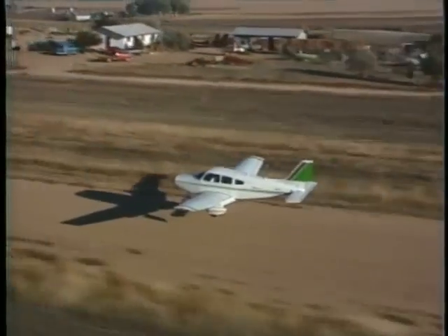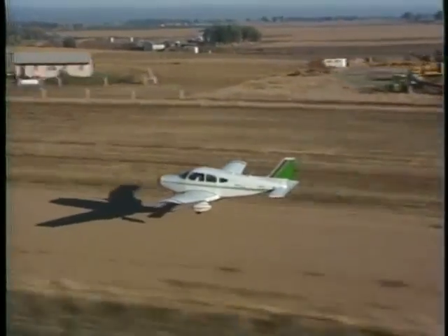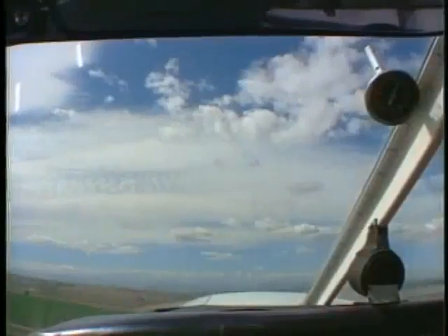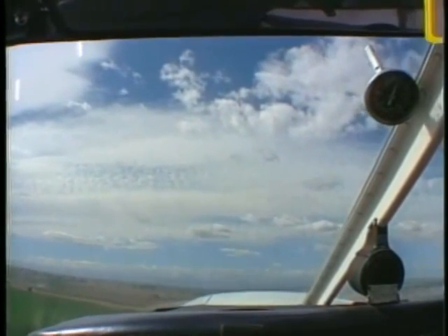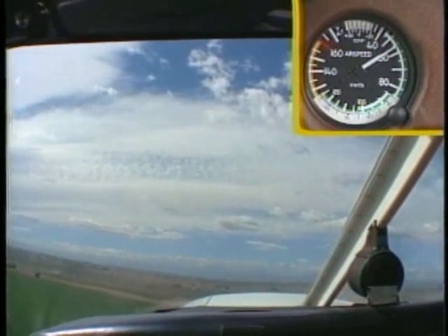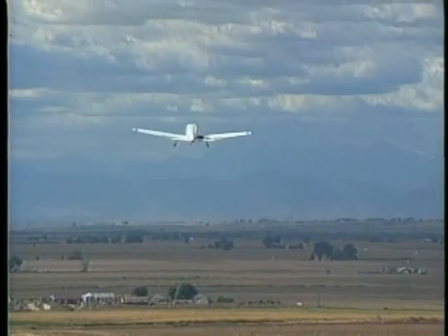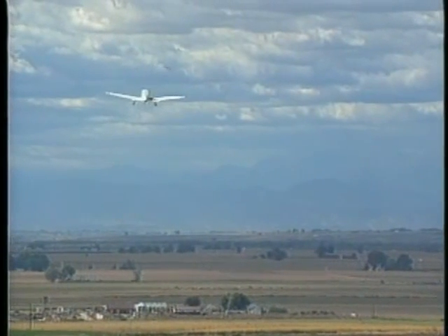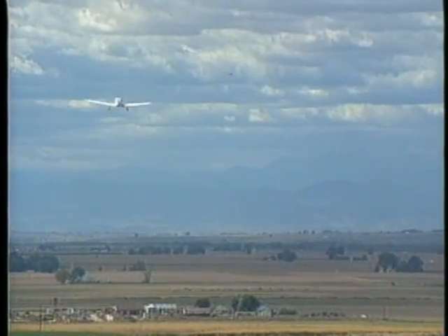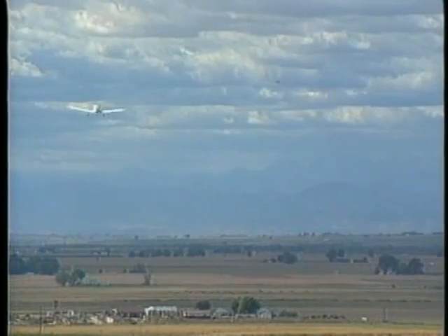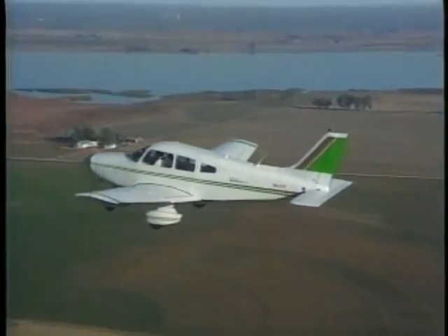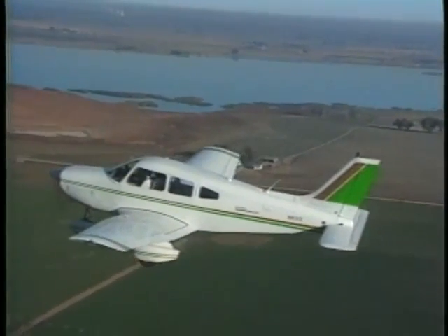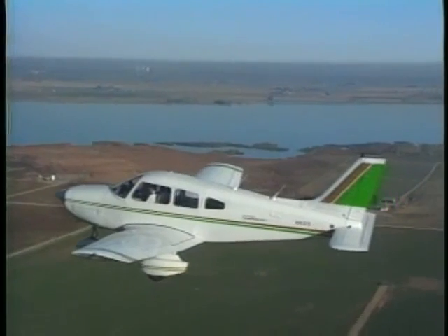Once airborne, lower the nose slightly and accelerate in ground effect, but make sure you keep the landing gear clear of the surface. If there are obstacles in your flight path, accelerate to VX or the climb speed recommended in the POH. If obstacles aren't present, accelerate to VY. Once you've achieved a positive rate of climb and can no longer land on the remaining runway, retract the gear if appropriate. When you are clear of all obstacles, raise the flaps according to the recommendations in the POH and complete the after takeoff checklist.